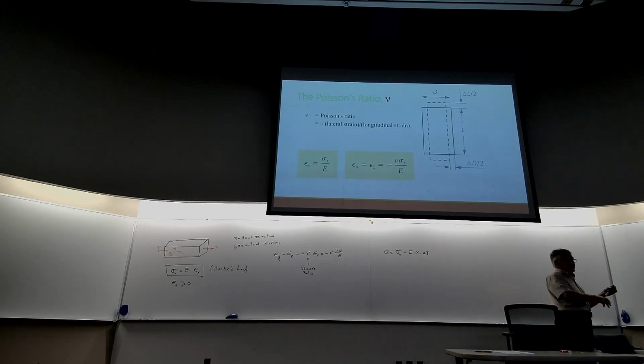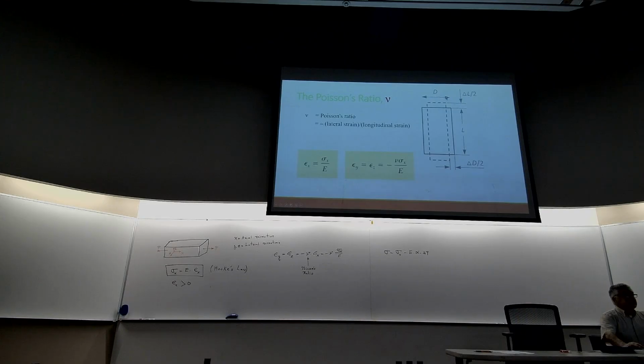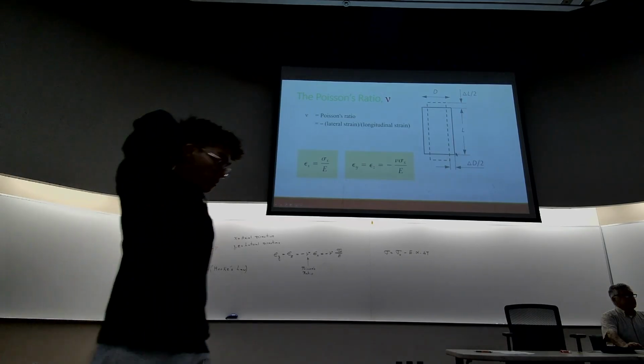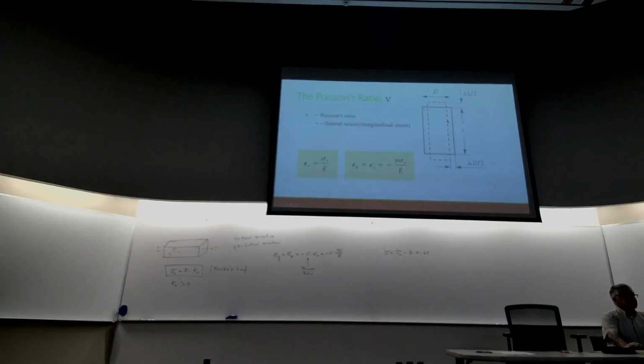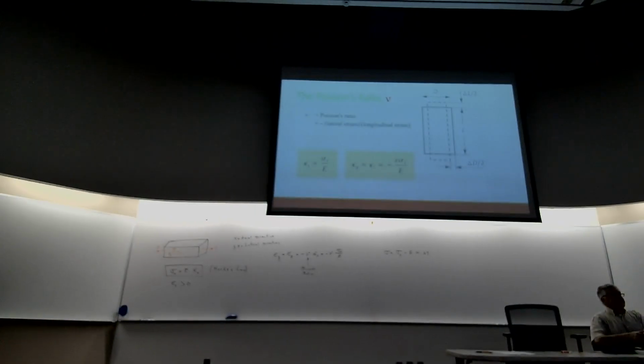Here in this figure, we have a cylindrical rod, so it has a diameter d shown here. And here we are applying the forces vertically, so axial is the vertical direction, lateral means in the cross section. The L gets bigger, the diameter shrinks in size, so we go from here to here. Smaller diameter, longer rod.